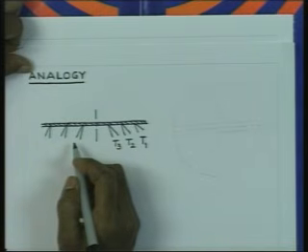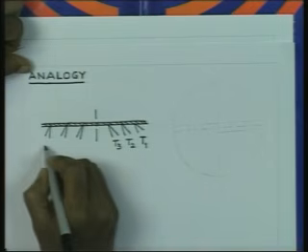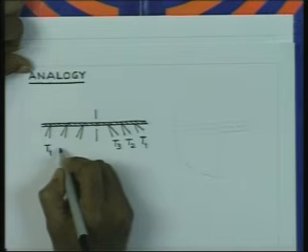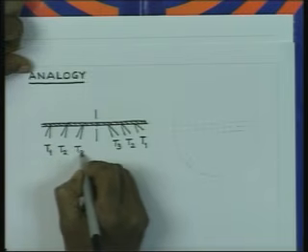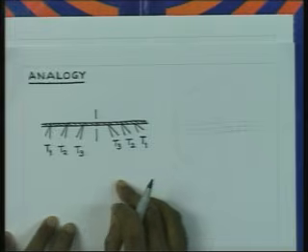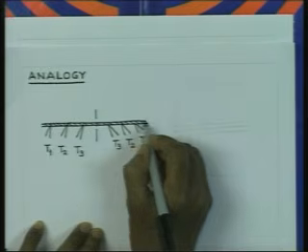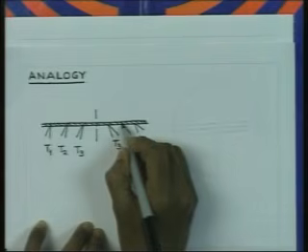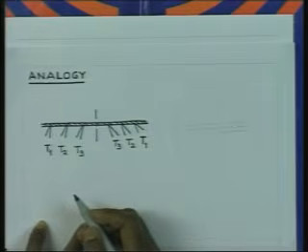Now, if we consider exactly the same situation in a tie, then you consider that this tension T1 is applied by the outermost person and then it is T2, then it is T3. So, here if you consider the tension over this portion of the rope, there is nothing and the stress is 0, but if you consider this to this portion, it is subjected to tension equal to T1 and therefore, there will be some stress.